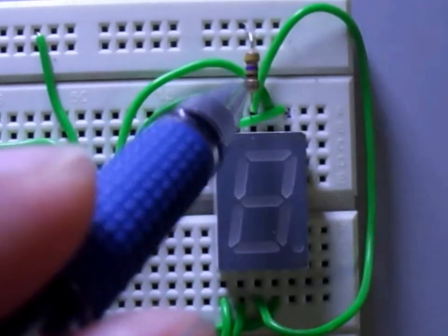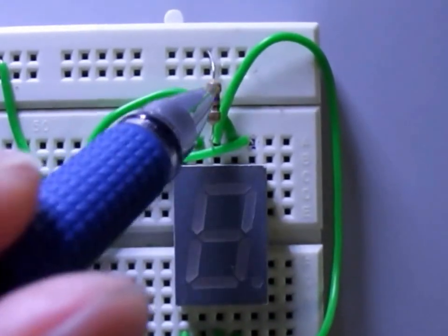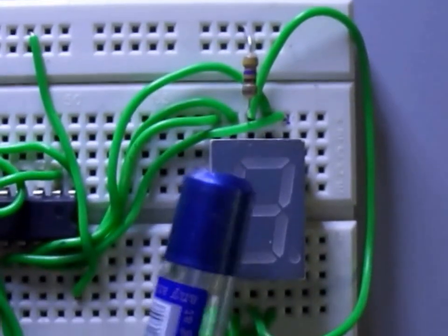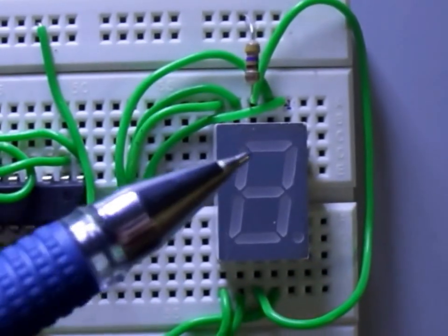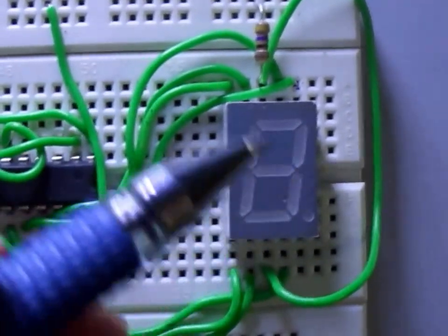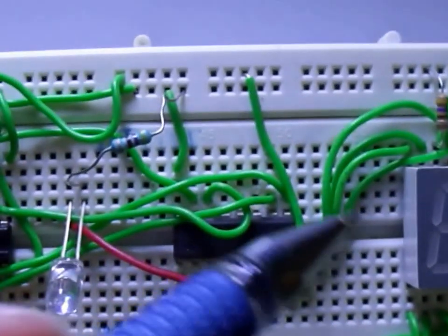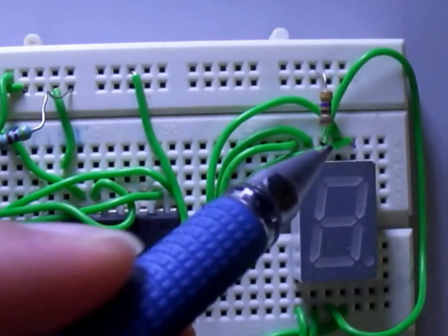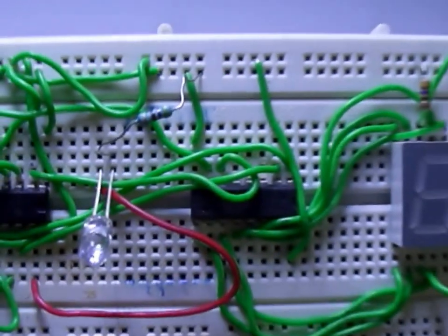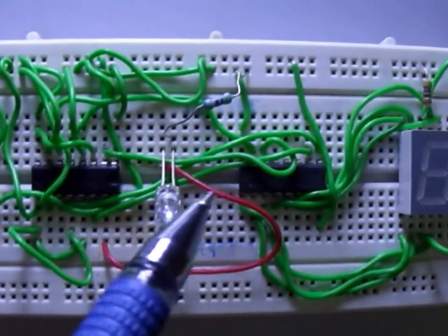So well, I'd like to tell you that this is a resistor that I have connected to the common anode. This is so that a less amount of power is consumed by this 7 segment LED. Otherwise a high current will flow through the 7 segments and LEDs could get destroyed, and even if LEDs are not destroyed, it will consume a lot of power, and so the rest of the circuit will get short of power.